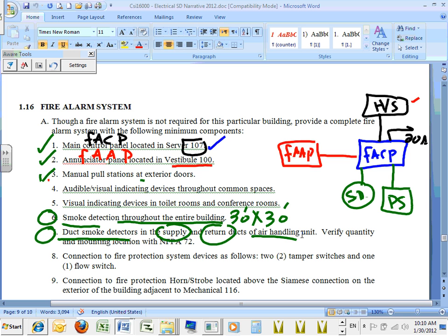Any questions, guys, about the smoke detector? So where do you want to put the smoke detector? When you reach them, we'll tell you where the inputs and the outputs of the air handling unit are. Two of them. One in, one out. Can I have thumbs up, right, Chad? We know it. So the second thing you need to do is duct smoke detector.